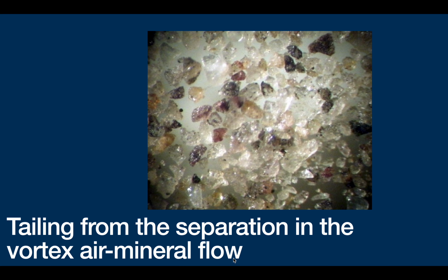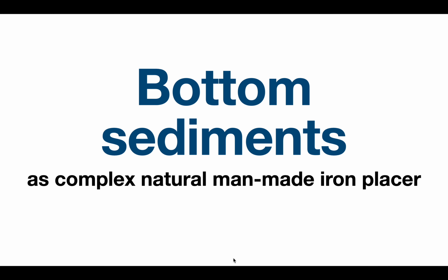Summing up, technogenic components and natural iron minerals are mixed in the river system. Due to it, the bottom sediments become secondary natural man-made deposits of heavy iron minerals. The processing of bottom sediments is only one of the ways the technology can be applied. It is suitable for recycling of tailings, slags, and heaps. Presented results are only the introduction to great research. We show only the possibility of such enrichment.